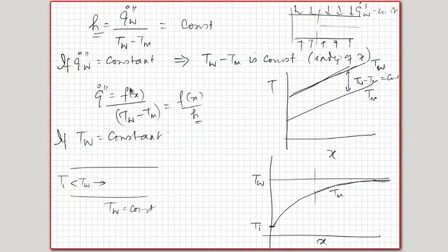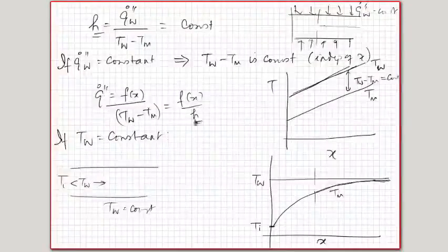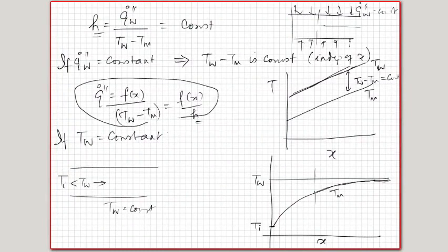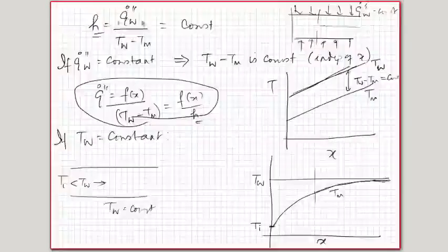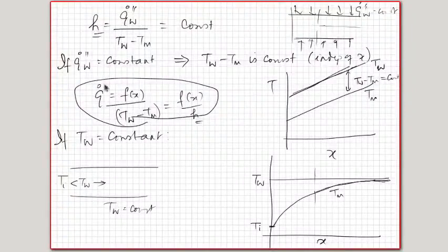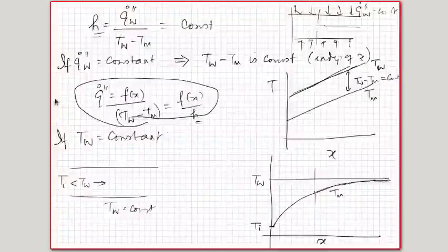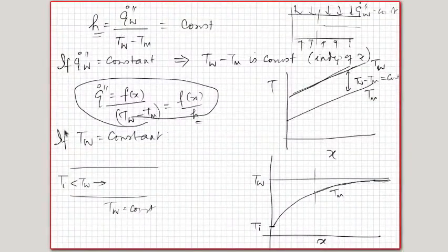So these two will have the same trend with just a ratio. Okay. So this is basically what we have derived, irrespective of what the boundary conditions are. The fully developed region is a place where your heat transfer coefficient becomes a constant. Okay. So hydrodynamically fully developed region basically means your velocity profile doesn't change any further, but the temperature profile will have to change in order to accommodate heat transfer.